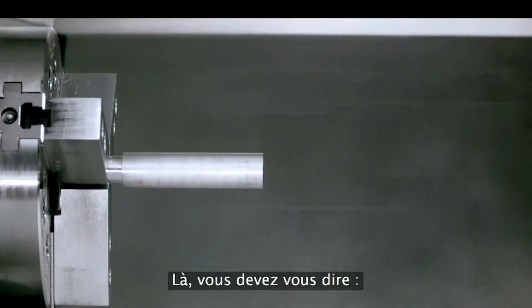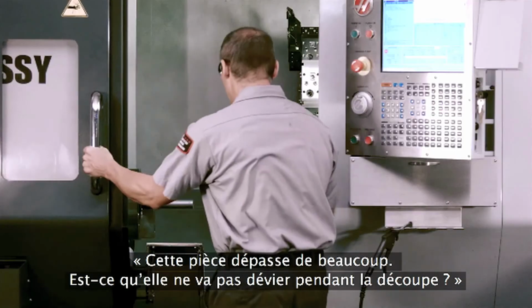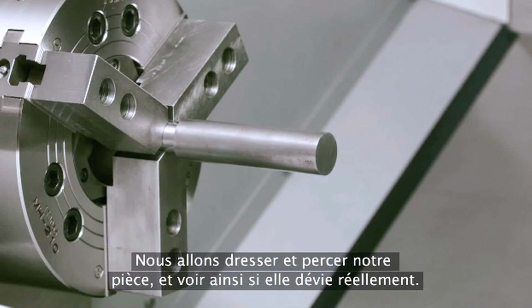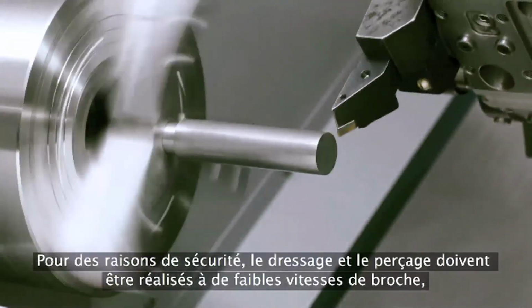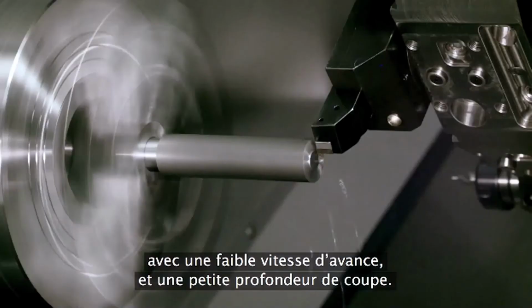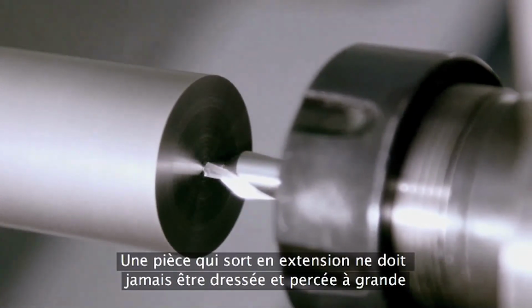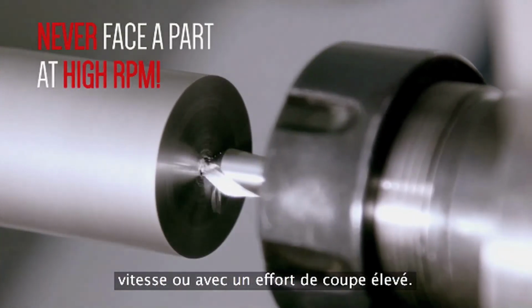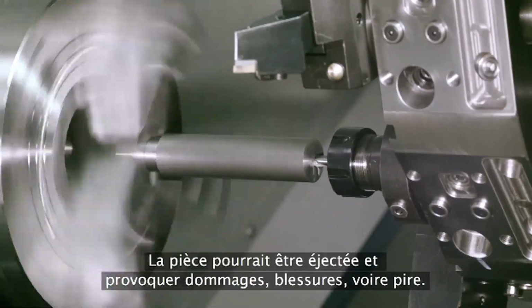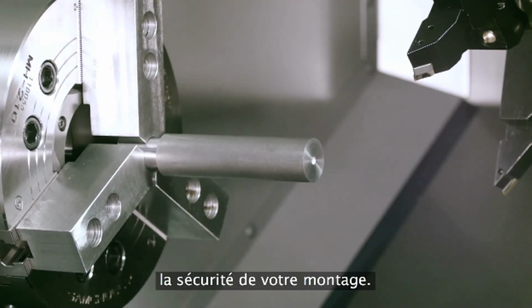You might be thinking, I've got this part sticking out pretty far. Isn't it going to deflect during the cut? Good question. Let's face and center drill our part and see if it does deflect. For safety, the facing and drilling should be run at slower spindle speeds, with a slow feed rate and a shallow depth of cut, so the shaft won't whip or bend. An extended part should never be faced and drilled at high RPM or cutting loads. The part can be thrown and cause damage, injury, or worse. Exercise caution and common sense when deciding what's safe for your setup.